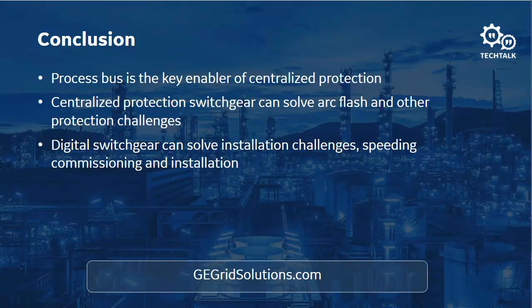The other problem that I have with, well, there are some other problems. The HSR ring does not give me a way to segment and control my network traffic like a managed Ethernet switch would. So that could cause me some problems.